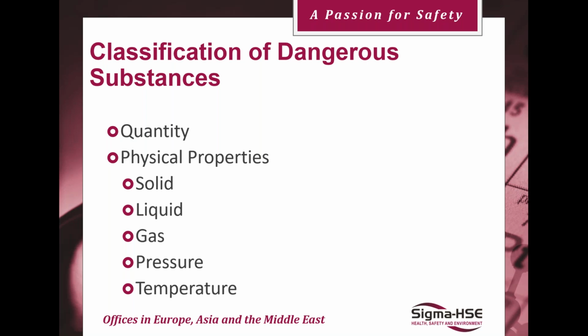And of course, it's a lot harder to keep tabs on in that particular form. So it's the way you handle these substances as well, whether they're solids, liquids, gases, and the conditions under which you handle them. Lukewarm water is all very well to be handled. We don't tend to do much harm with that. However, steam is considerably more hazardous. So the conditions of pressure and temperature under which you do your processing all have a potential impact on how hazardous your materials end up being and what the consequences might be if you actually lose track of it and have a loss of containment.